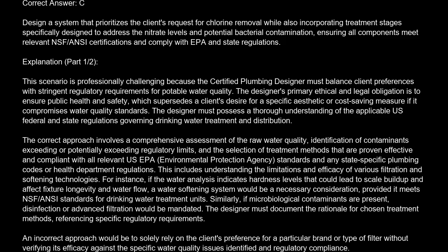This includes understanding the limitations and efficacy of various filtration and softening technologies. For instance, if the water analysis indicates hardness levels that could lead to scale buildup and affect fixture longevity and water flow, a water softening system would be a necessary consideration, provided it meets NSF/ANSI standards for drinking water treatment units. Similarly, if microbiological contaminants are present, disinfection or advanced filtration would be mandated. The designer must document the rationale for chosen treatment methods, referencing specific regulatory requirements.